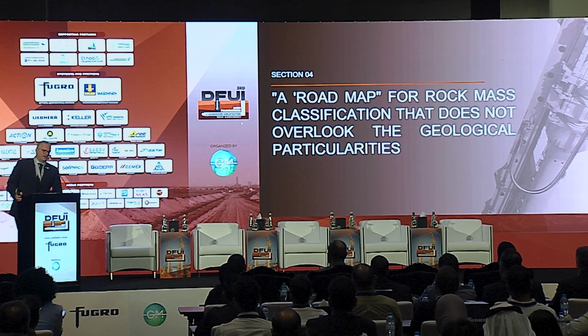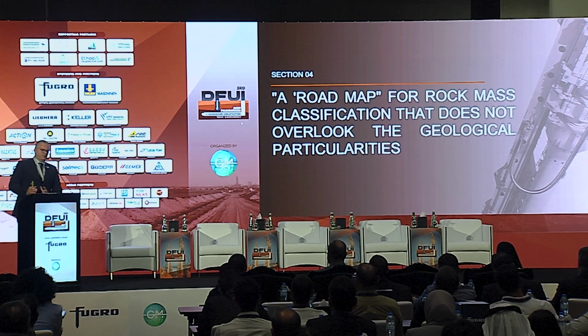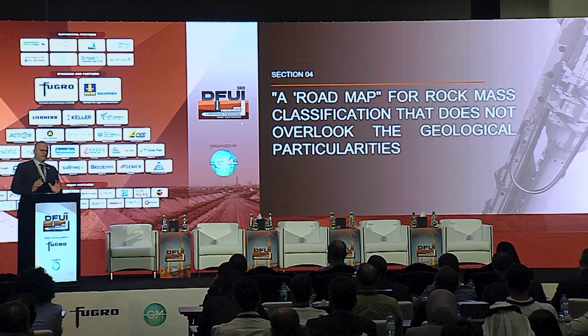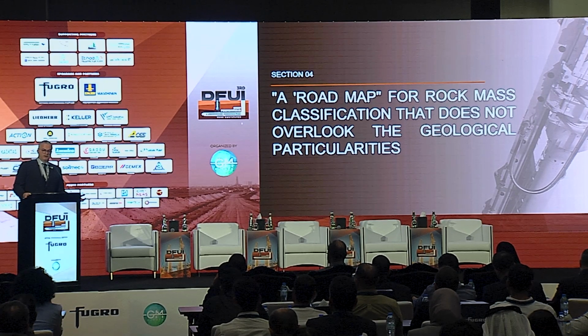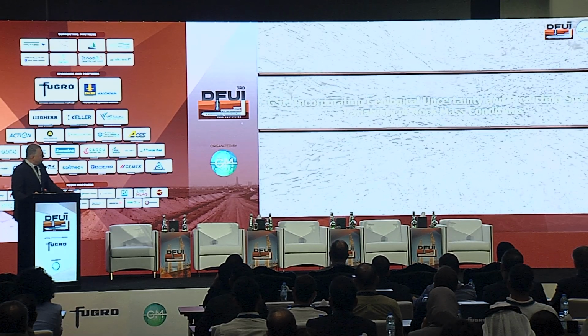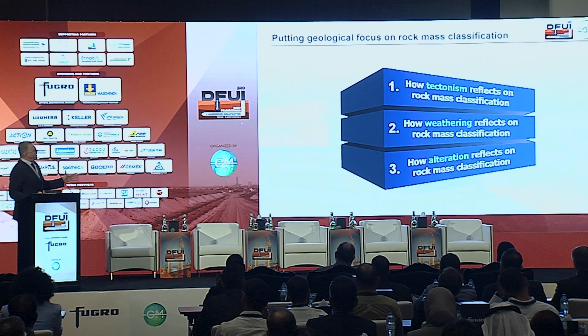When we use these rock mass classifications, since they are empirical, we need to find a way not only to help us assess the properties, but also to help us not lose any other kind of geological hazard that we can have in our project. So let's use this GSI incorporating the geological uncertainty, which was also our primary goal with the geological model, not only putting numbers. So how tectonism, how weathering, how alteration.